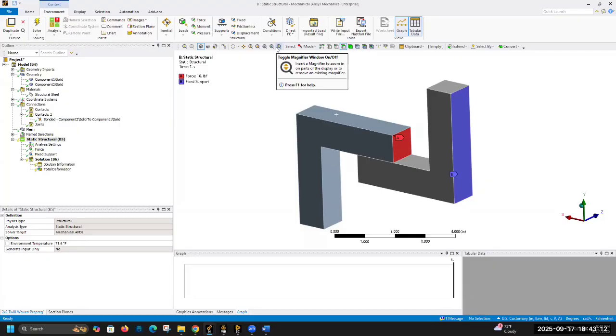And what does within reason mean? That is kind of engineering judgment. I know that's not the best answer, but sometimes correct order of magnitude is good. Sometimes getting within like 15% is good. So I wouldn't worry too much if you're a bit off. I would just make sure you know what you're probing. Let's say a hand calc says the highest stress is meant to be somewhere, but then you're probing the highest stress in another location. That could be something erroneous. Yeah, makes perfect sense. Thank you guys.